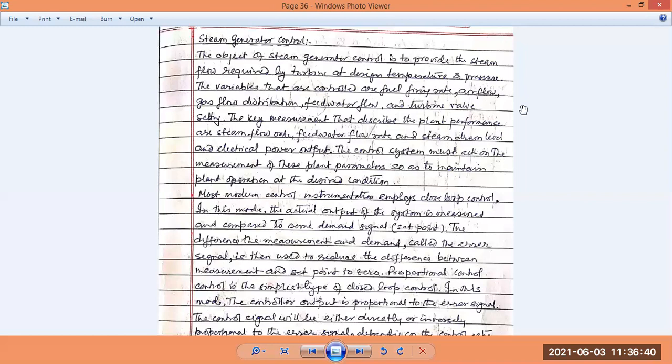So you have to control the air, and you don't have much control over the fuel because maybe only this type of fuel is available to you. You cannot change it, and this is the amount of fuel you can burn in the burning capacity of a furnace, so this many tonnes of fuel is required. You cannot change it much, so you have to change the rate of airflow.